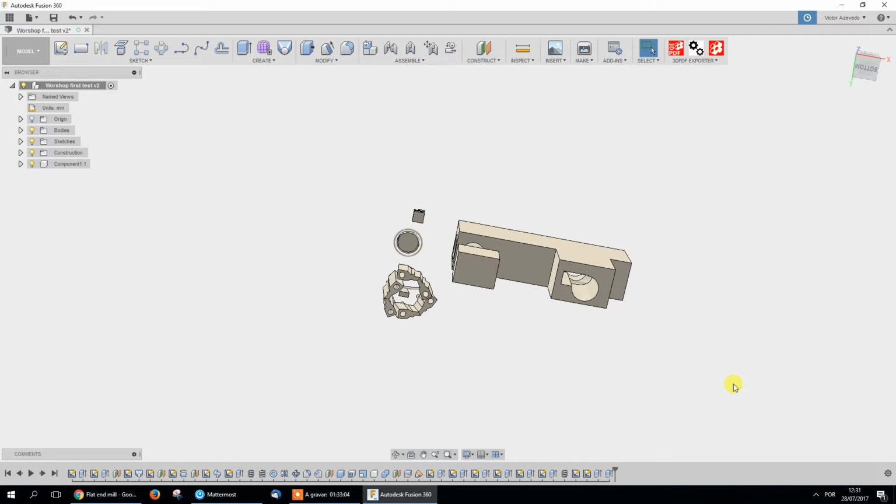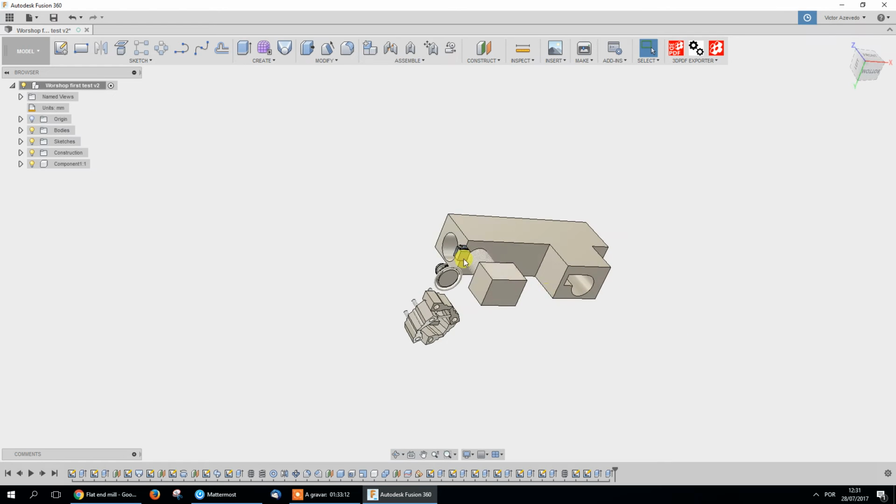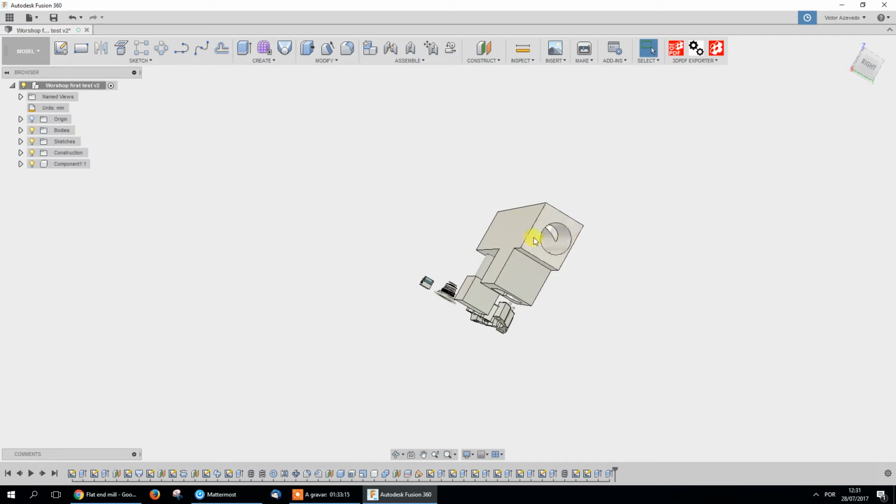So if I, let's say I don't have any reference to cut to remember this circle going here. If you don't have any reference to do that and you have to put a specific distance, you can then cover or close the hole with a new feature after. But if you want to keep the feature, you have to do it before. And as you can see, you can move the sketches. Of course, you can't move too far back or it won't have any reference there.